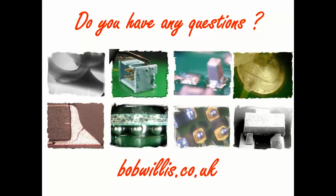Okay. What is your opinion or interpretation of standards about the need to coat solder mask? Well, in my opinion, solder mask should never be used as an insulator, although it has insulating properties. So if you've got solder mask, you shouldn't need to coat it. So yes, I would agree with what I think you're suggesting. So no, the design engineer defines what is necessary, and 9 times out of 10 it is the terminations, the termination pads, and in close proximity to those terminations.